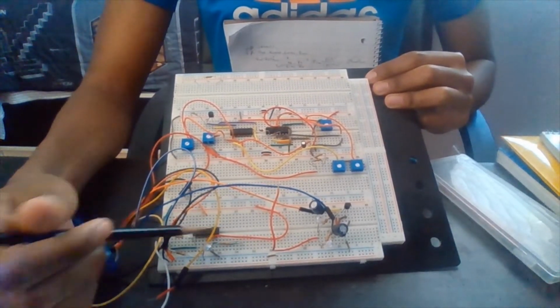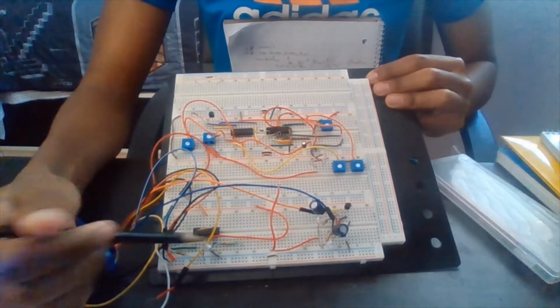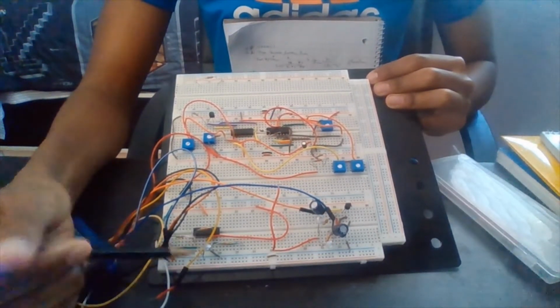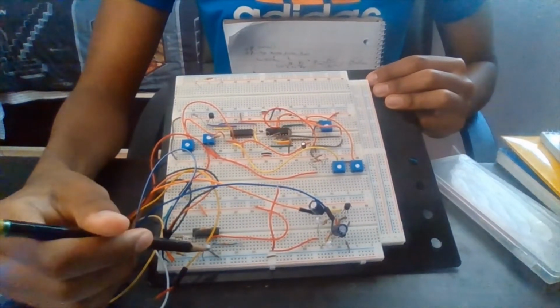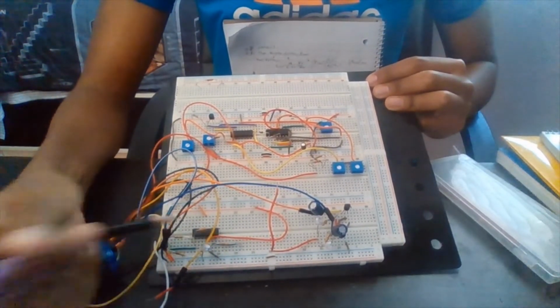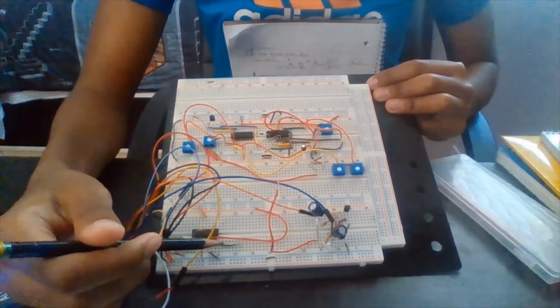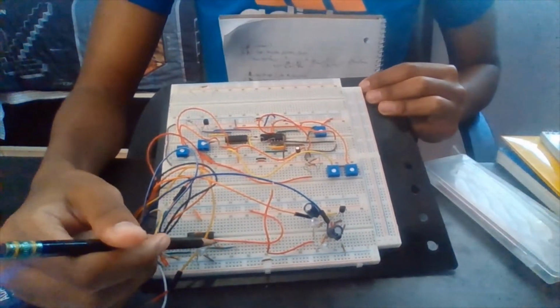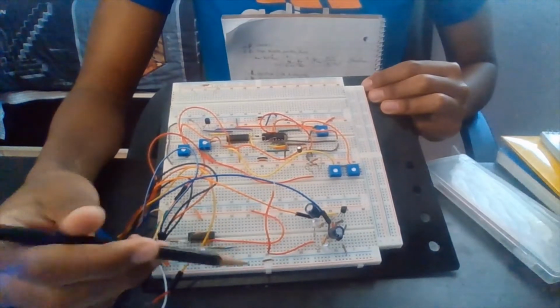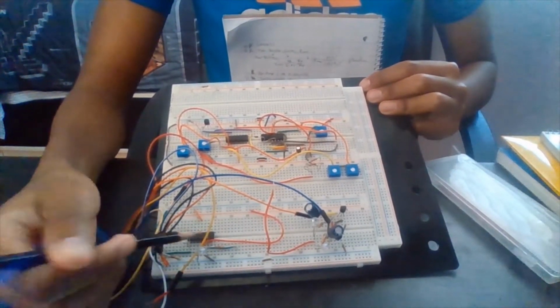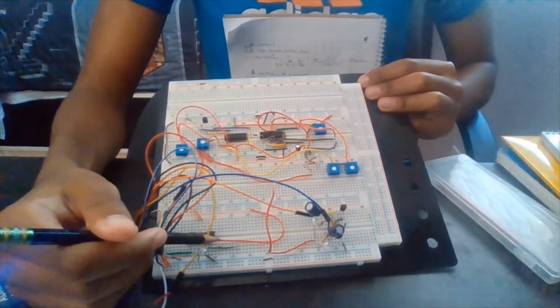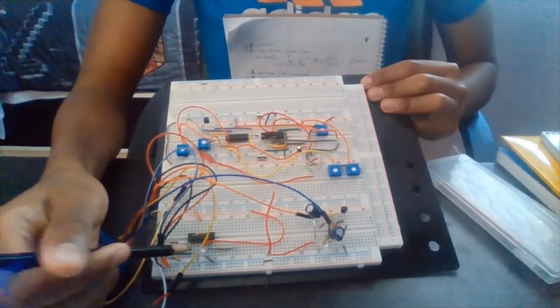Then over here we have the inverting amplifier. Essentially this is necessary because the diode is reversed, which is the only way for voltage to be across it, so the output is going to be negative, and we have to invert it. I just used a 4.7 kilo ohm resistor and a 2.2K resistor. So this is our input. The output should be a heavily amplified version of the input.